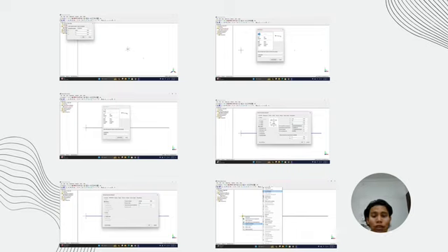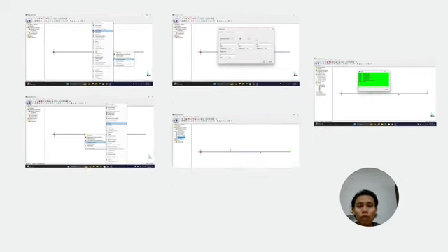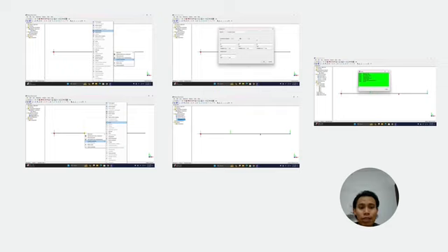Right click on the first node on the left and choose constraint, and then click on fixed support. While for the node on the right hand side, we will click on pin support. We will select the node that will be assigned the forces and insert all the data. So the result is shown as the first node is assigned pin support, and then the forces, and the next node is fixed support, and the last one on the overhanging side will have forces. And lastly, we will click solve to run the solution.